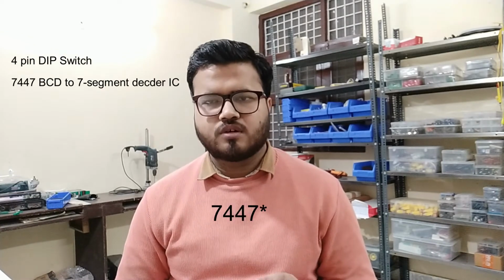Okay, so first of all we need the components for building a circuit. First, we will need a 4-bit input data, and I'm going to use 4-bit dual inline package switches. Then we will use a 7441 IC which will actually convert the binary into decimal for a 7 segment display, and at last we will need a 7 segment display. I'm going to use a common anode 7 segment display, and you can also use a common cathode, and we will need 4 10k resistors to pull down these switches.